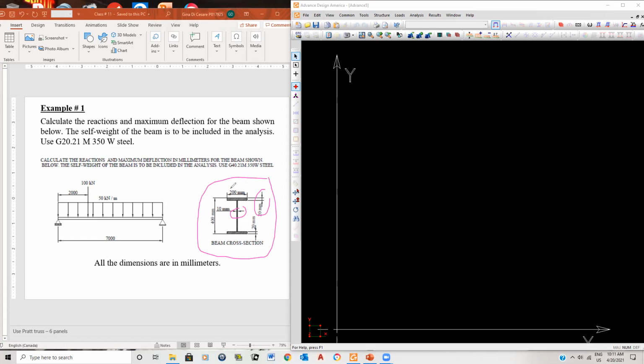So you'll be able to add this into the database, and ADA will then, from the information you give it, be able to calculate the properties of the section that it needs to use to do its analysis, and so on. And of course, you can do the same thing when it comes to materials. For example, ADA has 3 basic materials built into the database. You have one for steel, one for concrete, one for wood, because those are the 3 most typical materials that people design structures with. But if ever you want, you can even add aluminum, and then you have to put in all the properties of your aluminum, and then ADA will take aluminum and use that in its calculation. So you can even modify materials if you want to, but right now we'll just worry about sections.